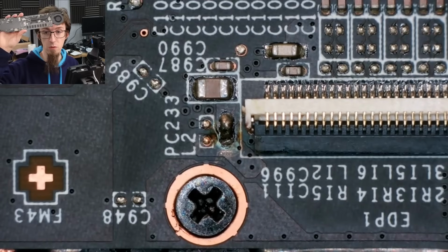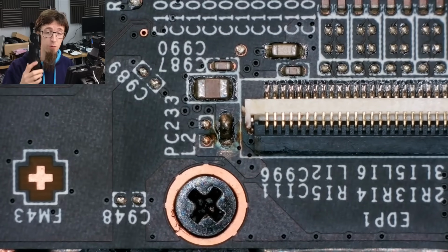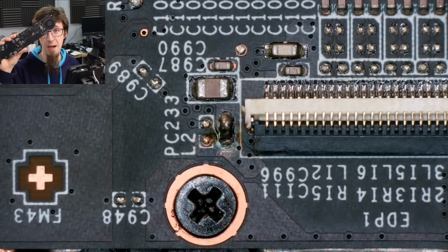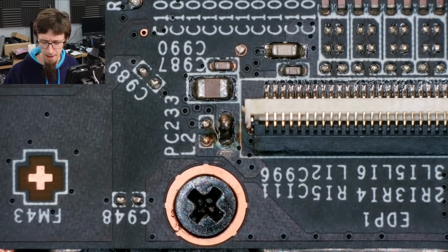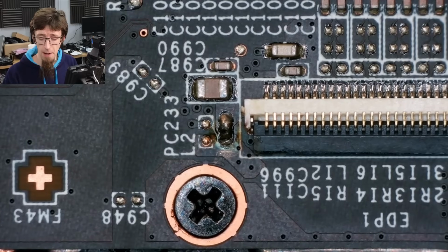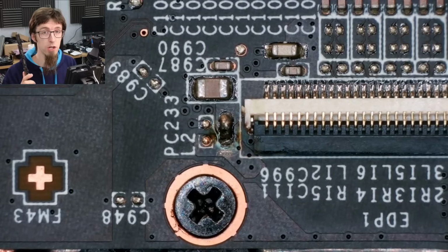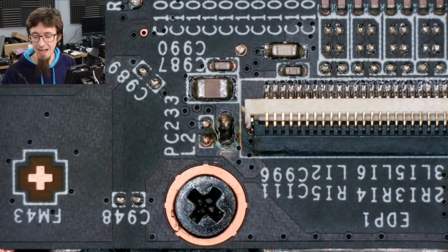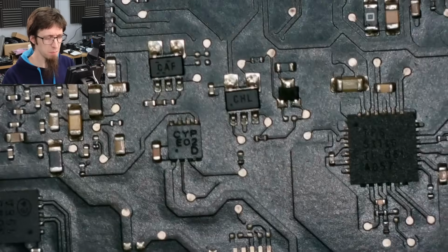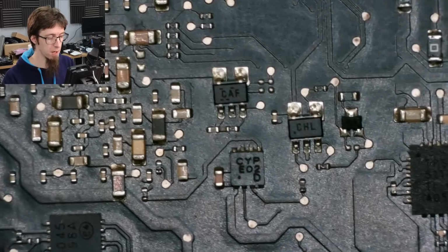boards are MacBook boards. And old MacBook boards can be, this is an ancient MacBook Air board like 2011 or something irrelevant like that, these can be great donor boards because the MacBook logic boards are so well documented that we've got really good schematics and board views for them. And that means it's really easy to find parts on these and know where they are and take them off these boards. So I had a look around on the back of this logic board for some small inductors that looked about the right kind of size, just ballparking.